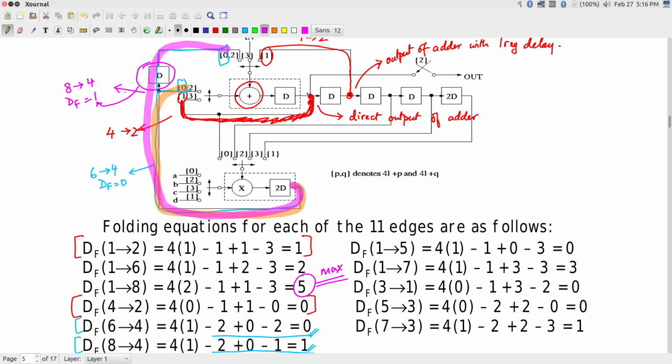For example, if you look at this particular delay element, this register out here, it is basically the output of the multiplier being put through one register and then being provided as input to the adder at phase 0 as well as at phase 2. Now the fact that I could use that particular register in order to do both of those was not entirely obvious from the original design. That I could share this particular register.